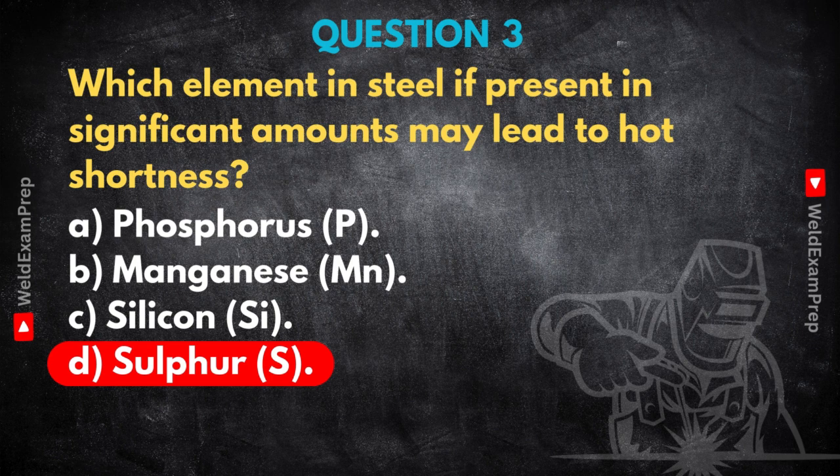How does that work? Does it completely solve the sulfur problem? Good point. Yes, manganese, Mn, is key. It's added deliberately, often called a scavenger. Manganese has a higher affinity for sulfur than iron does, so it preferentially reacts with the sulfur to form manganese sulfides, MnS, instead of those nasty iron sulfides, FeS. And MnS is better. Much better.